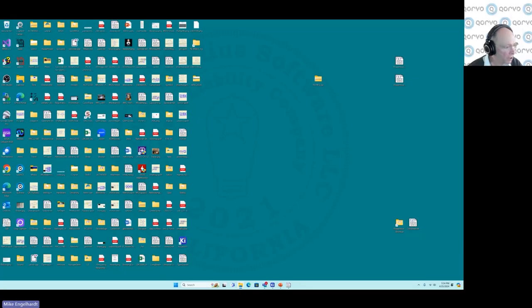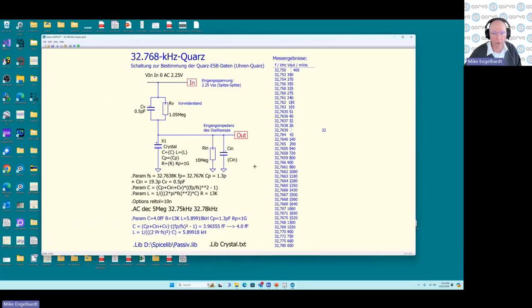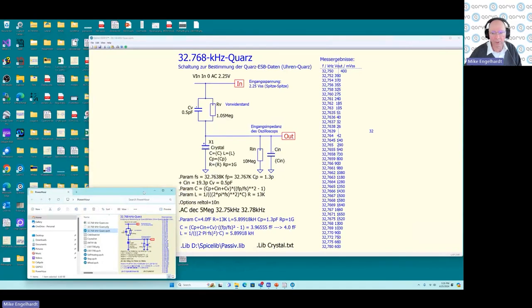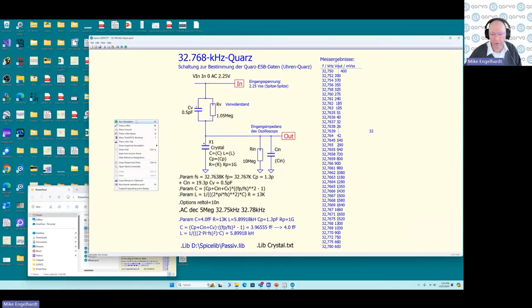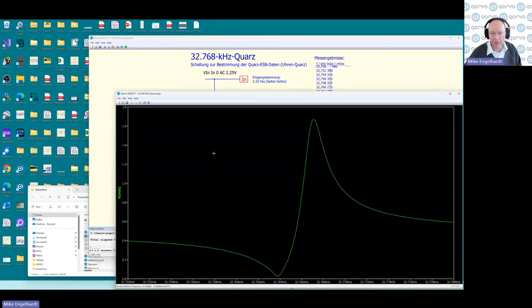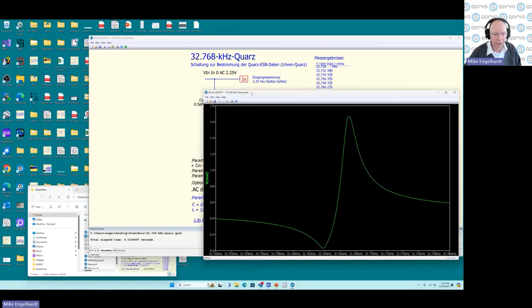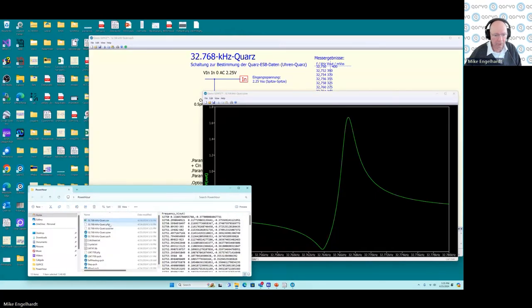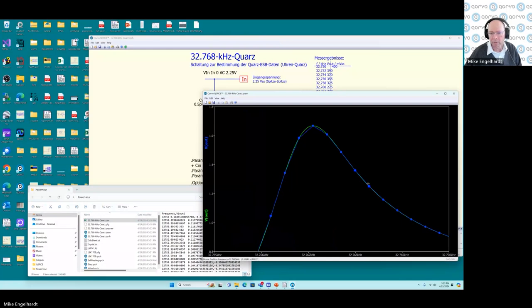And so the first thing I talked about is overlaying waveform data. This is some simulator data that a professor in Hanover sent me, and he wants to know whether or not his model matches the impedance curves he measured. So here I have an Excel CSV file, and I can just drag and drop it in and overlay it, which is useful.